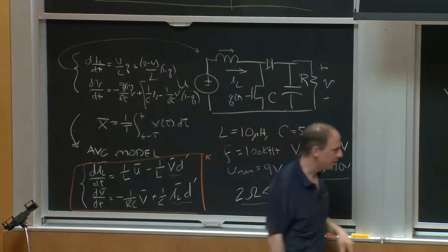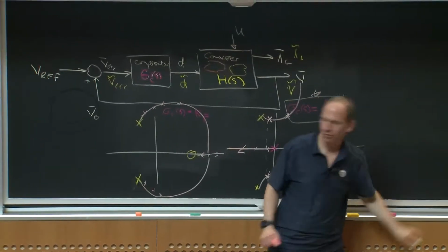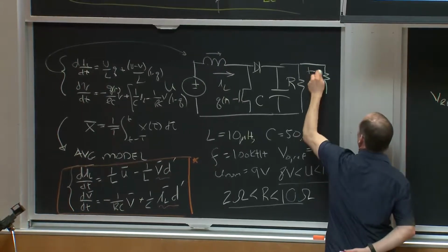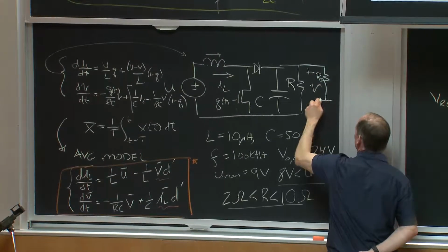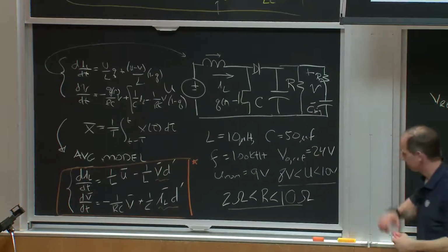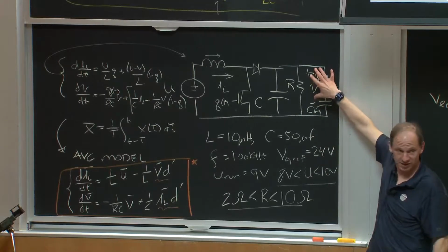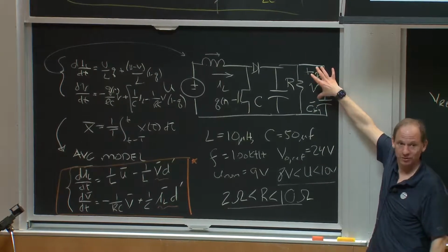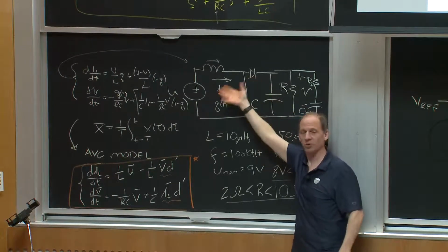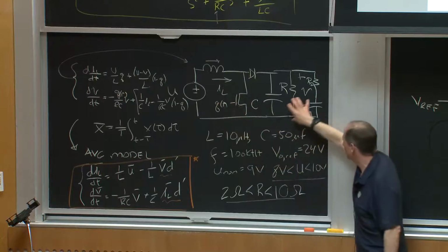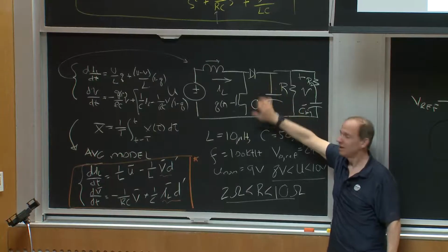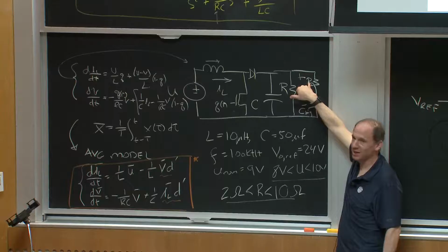Well, what happens if I walk up to this thing and I say, you know what? I will throw a damping leg on the output of this. I'll put another resistor in here, RD. And here I have C big. When we talk about filter design, you'll also see these kinds of damping legs, and you've seen it in snubbers too. The idea is, at frequencies near the oscillation point with L and C, if C looks like a short circuit, then RD is sort of in parallel with R and damps this. And then if R gets big or small, it always has RD in parallel with it.